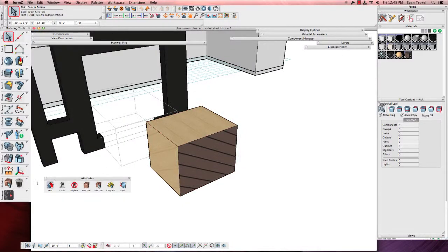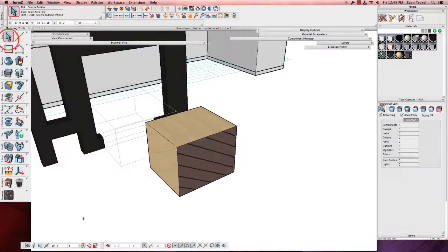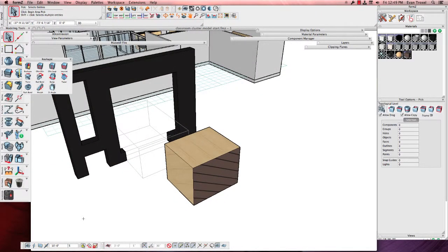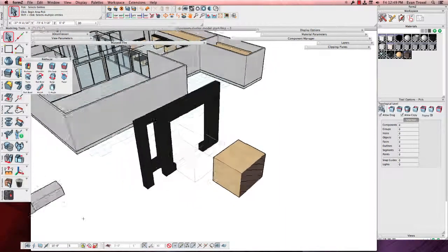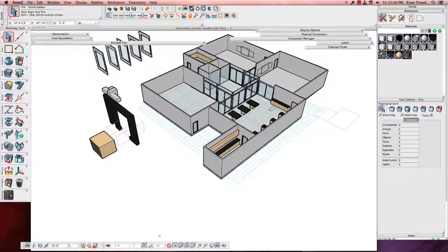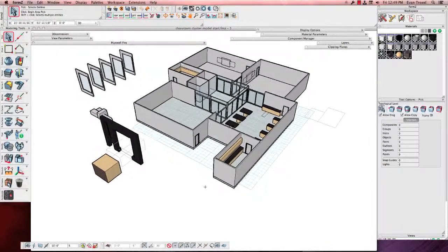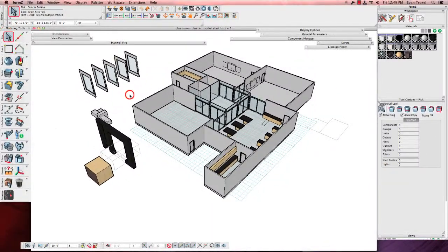Well, I'm not exactly sure what that means, but let me read the rest of the question. Maybe with groups unlocked or by setting topology to points and moving a selection of points. Say if a room size changes, I'm wondering how it affects parametric walls, doors, rounded objects, cylinders. Okay, so this is getting back to the thing I said earlier, where if you actually modify the points or faces of an object, they do lose their parametric abilities.